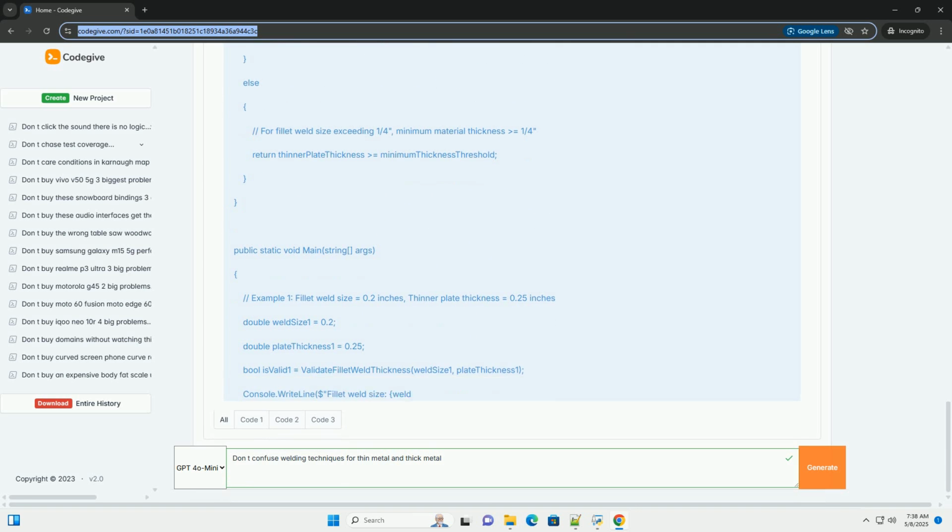Gas shielding: argon or argon-helium mixtures are common. CO2 or argon-CO2 mixtures are often used. Electrode size, SMAW: smaller, to concentrate heat and reduce current; larger, to handle higher amperage.